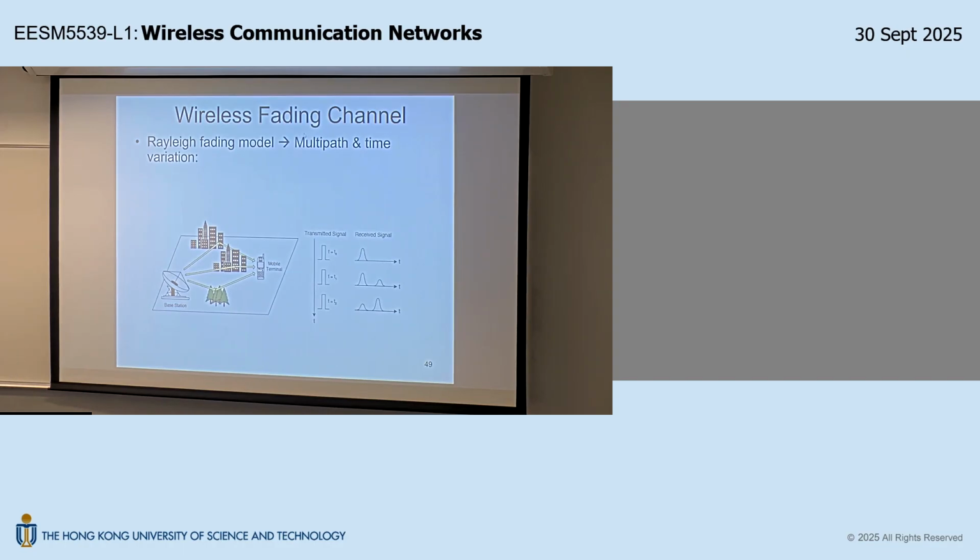So what I illustrated is deep space communication, point to point, the ideal scenario. But in terrestrial mobile communication, there is usually more than one path from the transmitter to the receiver. When you add up this multipath effect, the path loss formula can be more complicated. So you may have a relationship of 1 over d to the power alpha. This alpha is called the path loss exponent.